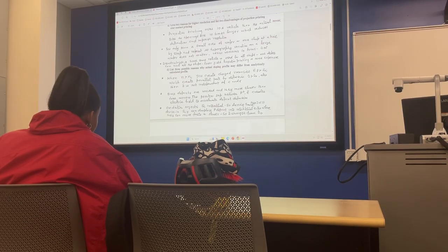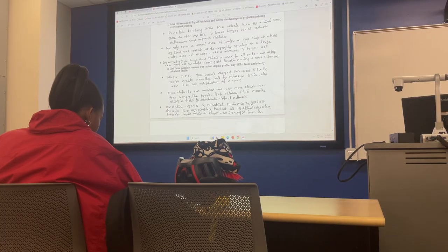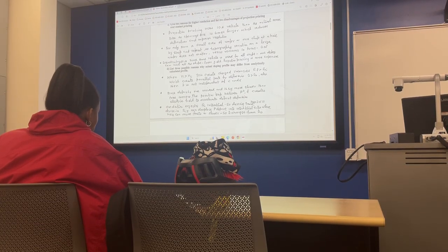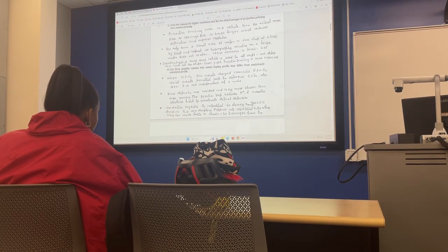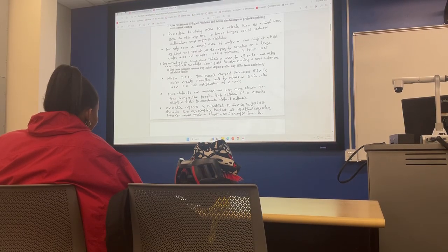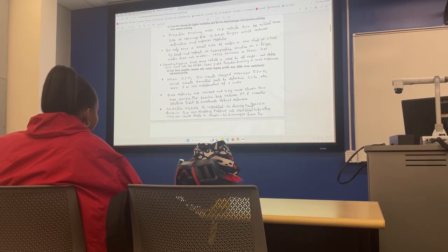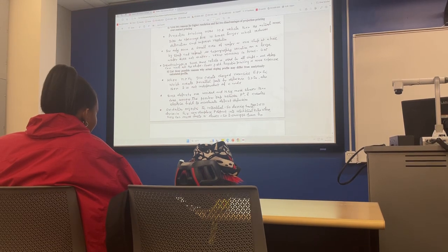The second, we talked about that you are doing diffusion at such high temperature, so all the dopants are ionized. So phosphorus is P plus and the electron is ionized. Now they both can move, but electrons can move much faster. So if electrons are here and the P plus is here, there is an electric field between the negatively charged electrons and the ions.